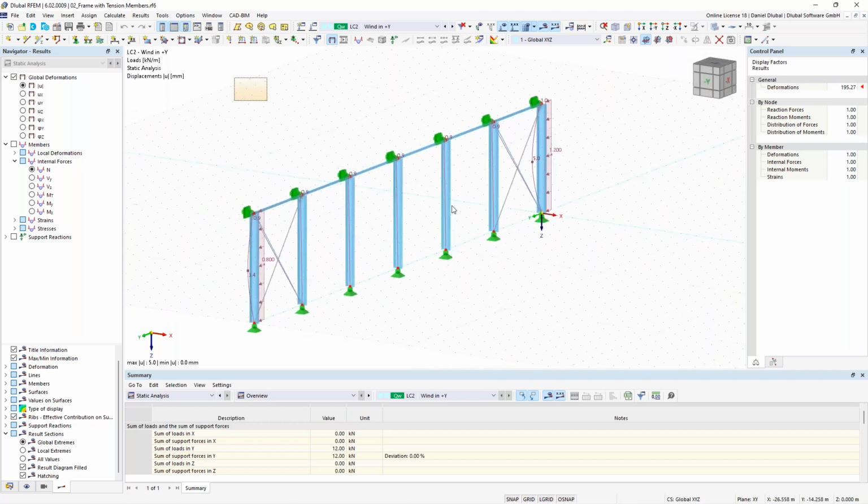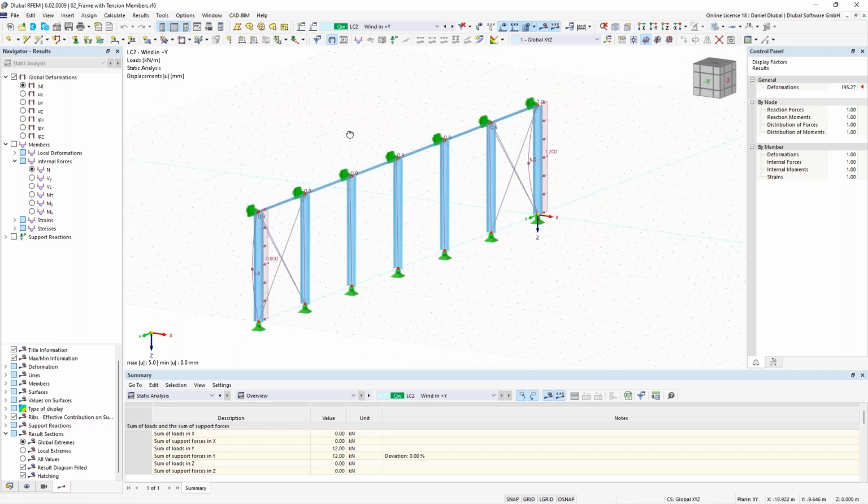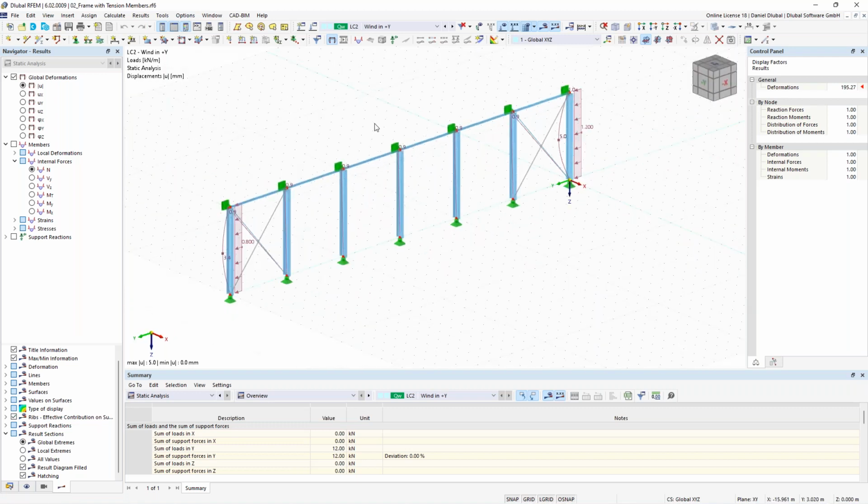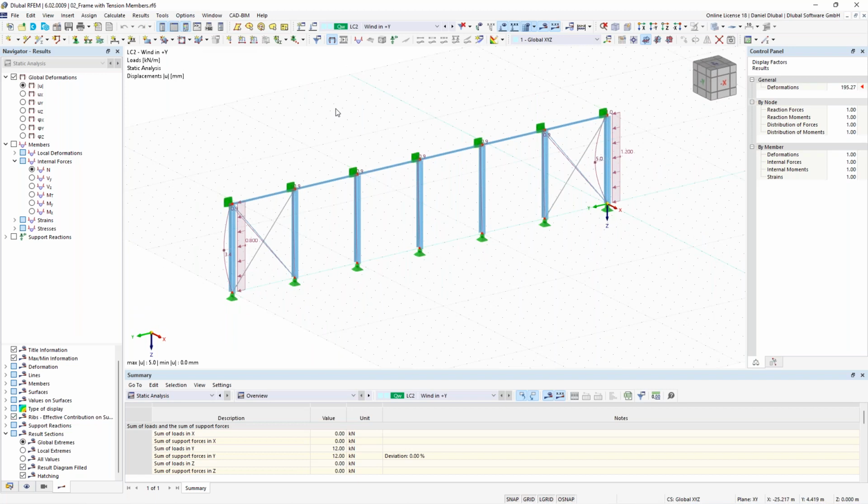So we have this one side, and you can imagine that with this column we also have some beams for the roof, but in this case only this one side is considered. Now I have to stabilize it by giving it a kind of bracing, and we see these bracings here.